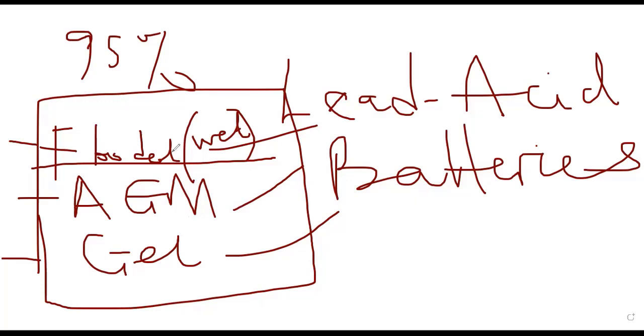It also depends on application, on where you are installing this system. If you are installing the system in a telecommunication facility, you may want to go with a maintenance-free battery. So it depends on application, it depends on usage. Apart from this, you also have the lithium-ion batteries. These are the new technology that companies are pushing out there now, because it has a high energy density. Let me explain something.